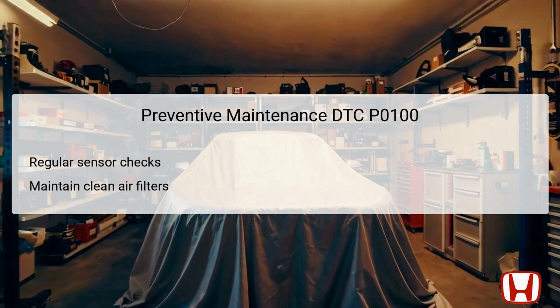Preventive maintenance is key to avoiding DTC P0100 in the future. Regular checks on the MAF and IAT sensors can help catch any issues before they escalate into substantial problems, ensuring accurate airflow measurement is maintained. Additionally, maintaining clean air filters will prevent contaminants from affecting sensor operation and prolong the lifespan of the MAF sensor.